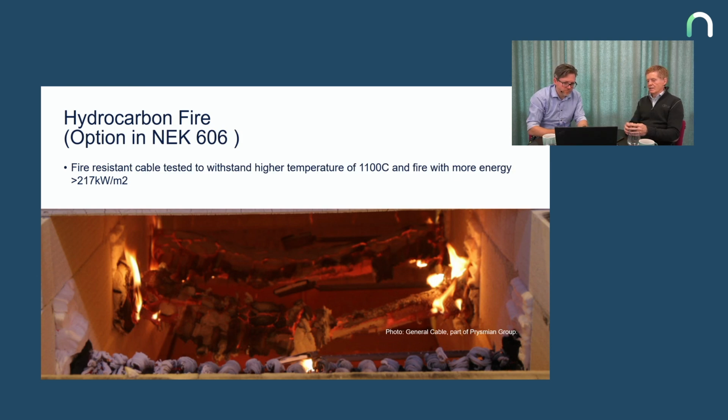So where you have the pool fire, the hydrocarbons burning, we have a fire curve that goes higher than the normal cellulose fire that is used in the IEC 60331 part 1 and 2 standards. So this is a higher temperature, more demanding test. And it's burning with 10 or 12 burners in a big chamber like this, not a single flame burning just a part of the cable like the 60331 test.